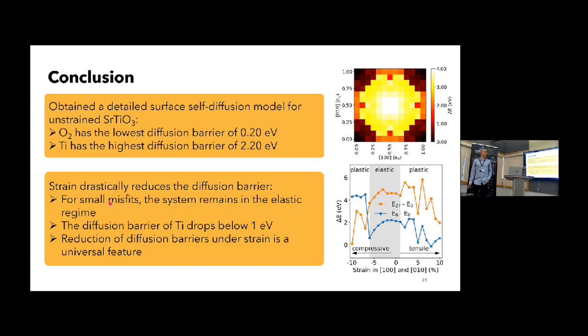No, first of all, for the oxygens, it's produced under oxygen flow. We assume no oxygen vacancies, at least not in any significant amount. And the other thing is, we deposit at a really high temperature. So during the deposition, the material can already go to this crystalline state. So we assume, since it's still work in progress, that during this time the atoms are deposited on a flat surface.